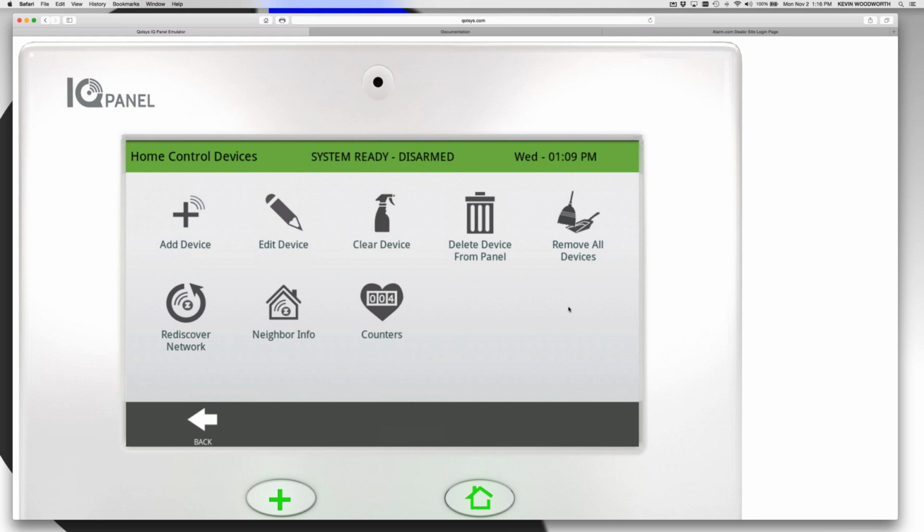And I think early days, luckily we're a couple years in here and most of the industry is adopting Z-Wave, but early days we would see a lot of dealers try to put that thermostat on the other side of the house, right? They put the panel by the garage door, and maybe it's a big ranch style house, and they install one smart thermostat all the way at the other end of the house outside the bedrooms in the hallway. That's a pretty typical layout. And what they would find is that thermostat would have a lot of issues communicating and would work intermittently if it worked at all. And that's because Z-Wave is a very, very different technology than security sensor technology.